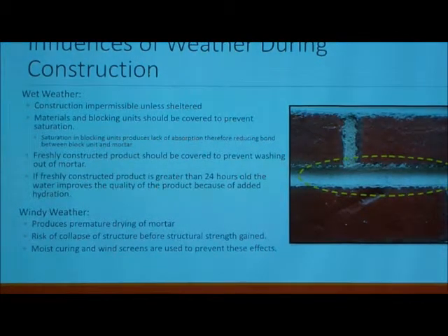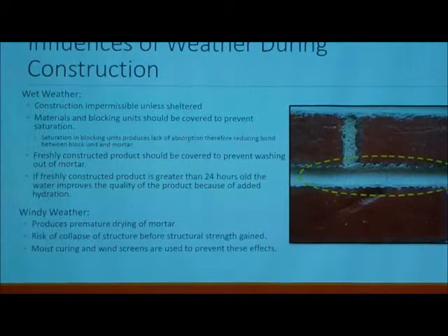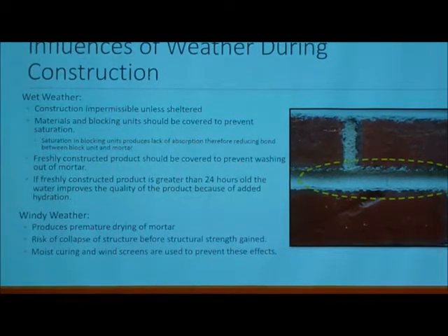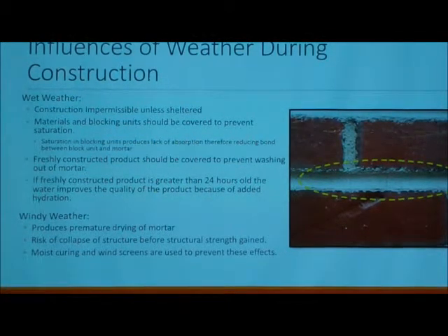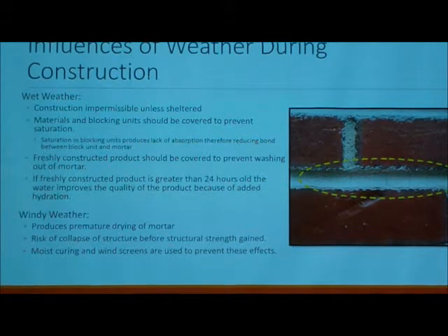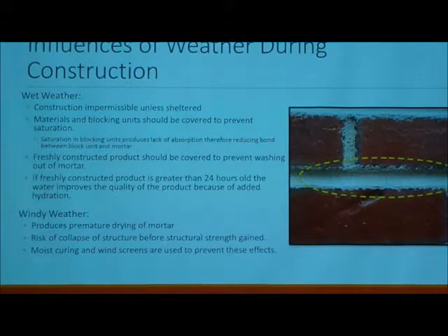Okay. Now we'll talk about wet weather. Wet weather construction is impermissible unless you're sheltering the actual construction blocks, so they do not get wet, because if the bricks are wet, then that affects their absorption rate because they've already absorbed water.